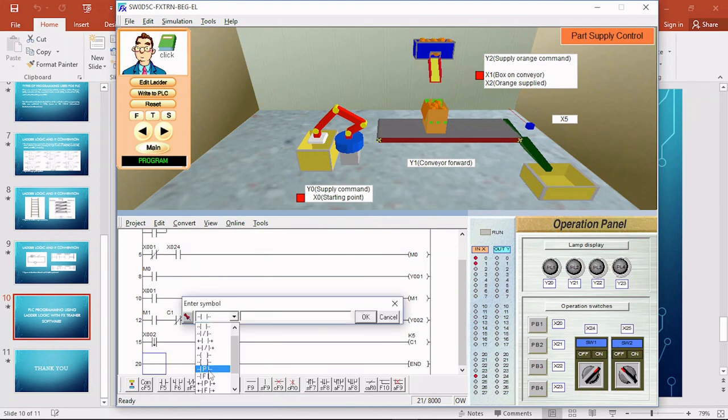then add another run here where we have the counter. In this case, I'll be using the counter as a rising edge, so I only want to know when the counter goes from 0 to 1. That's at the time the counter has already counted 5. At that exact time is when I want this to start.